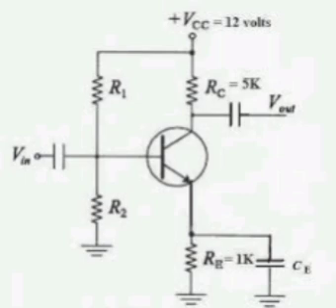Next question, 4th B. Determine the impedance ZL that results in maximum average power transfer to ZL for the circuit shown in the figure. Calculate the maximum average power transfer to the load impedance determined. Input voltage is 20 angle of 0 degrees. Voltage is connected in series with 5 ohms. Then the 5 ohms and 20 volts are in parallel with 20 ohms. Again series with j3 ohms. Again parallel with minus j6 ohms.